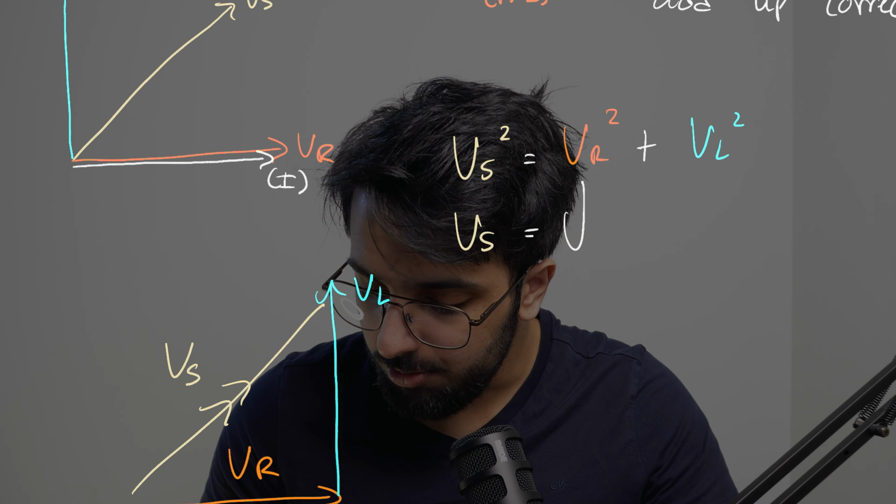And so what I recommend doing is using theta is equal to the inverse sine of VL all over Vs, okay? This L should be subscript. There we go. And so therefore our theta is equal to the inverse sine of VL, which is 7.8, all over 11.5, and this gives a theta value of 42.7 degrees. Okay, now obviously in this case we did get our voltage across our resistor correct, so if you really wanted to, you could figure this out and say 7.8 all over 8.45, and this indeed does give you 42.7 degrees also, okay?